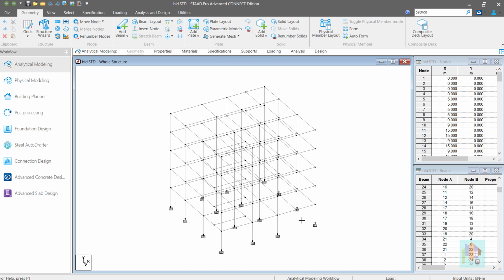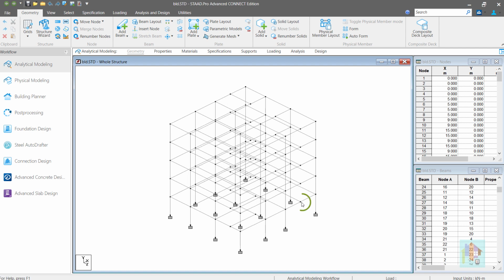Indeed, for a single member which is spanning between two columns or supports, it is not possible to provide hugely different design data. But using the analytical modeling mode, it is very tough to inform the program about this full member information. Also, we cannot omit the internal nodes as they are necessary for proper member-to-member or member-to-plate connection. Otherwise, force transfer will not be proper.